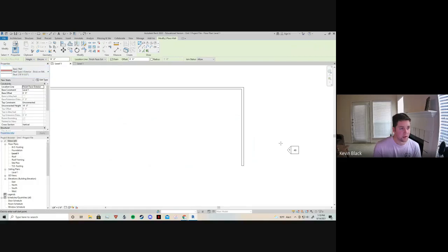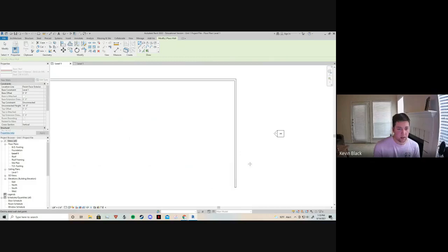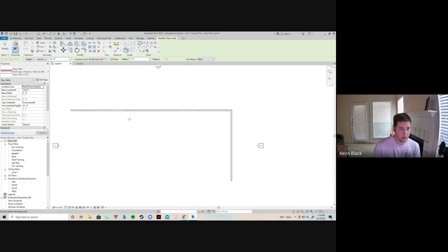So then we're going to go ahead and select our wall type 3. Just grab that exact same point and type in that 24. Then we can hit escape. So we've got the instance of wall type 4B back here. We've got 4A there, and we've got wall type 3 there.